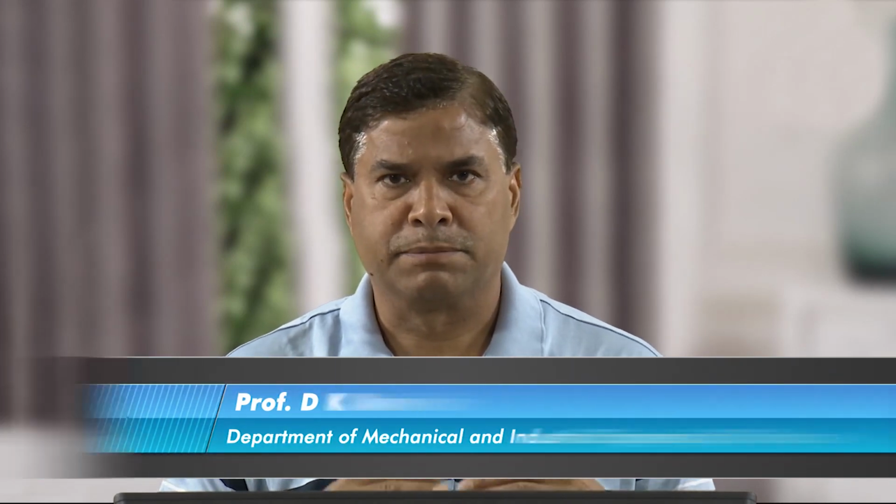In the previous lectures we have talked about the ways by which we can understand the weldability of metal, and especially that the weldability of metal is affected by three important parameters: the welding process, the purpose for which the weld joint is being developed, and the fabrication conditions under which a joint is to be developed. And there are three main ways which can be used to assess the weldability.